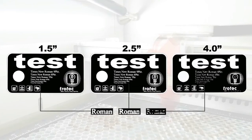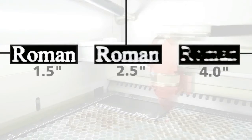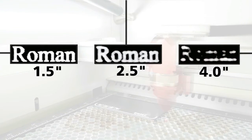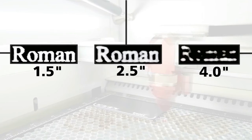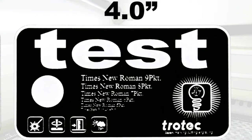And this happens due to the fact that the spot size is larger on the 4-inch lens than on the 1.5-inch lens. If we would boost the power using the 4-inch lens, it would look bold and not very clear in the smaller details. The reason why it looks like it does is due to the fact that we are losing energy, or it's less intensity, since the spot size is larger than on the 1.5-inch lens. Since we have less intensity on the focus point, you can see that details and particularly thin lines are nearly invisible. They are there if you would look under a microscope, and it would look like a shadowing effect.